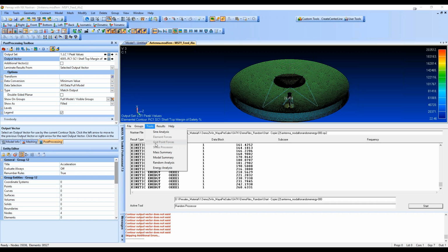And we predominantly look at the forces and the stresses, and we aren't looking at things based on margin until after we've looked at the forces and stresses. And we like to be able to, it's all the way from coupled loads analysis results, combining with acoustic, looking at random, looking at sine, looking at quasi-static load cases where we've got 96 load cases run and we need to find out what's the max.